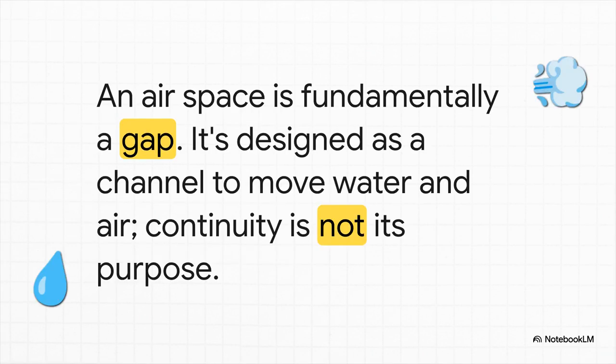So the takeaway here is super simple. The air barrier has to be continuous, but the airspace, well, it's fundamentally a gap. It's a channel. It's designed to move water and air. Its whole job is just to be empty.